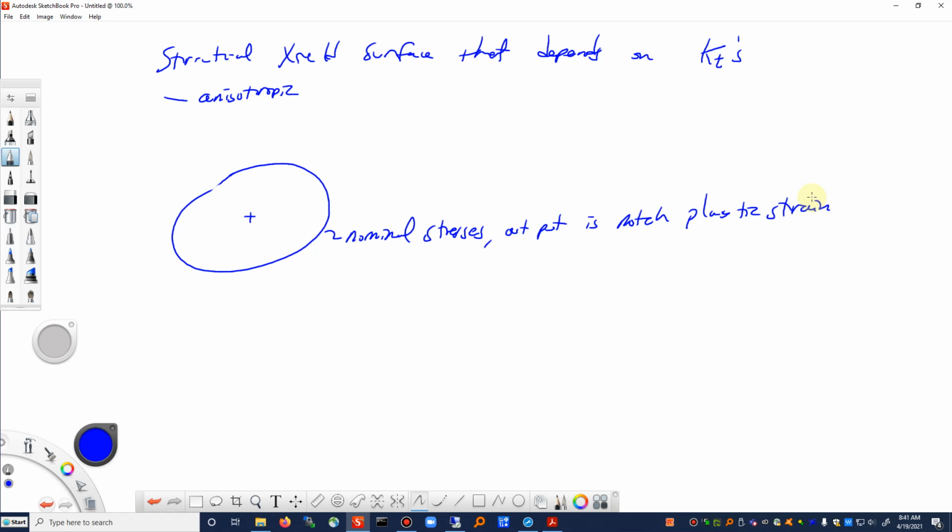What do you need when you have a yield surface model? Well, you need as input your yield criterion, the things that go into your yield criterion. We said that can be expressed in terms of the stress concentration factors. That's not a big deal. But you also need a stress versus plastic strain curve. In this case, since we're expressing this yield surface in terms of nominal stresses, this would be a nominal stress versus notch root plastic strain, and whatever shape that looks like.